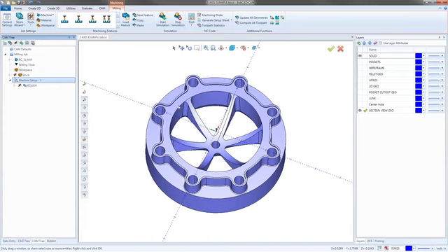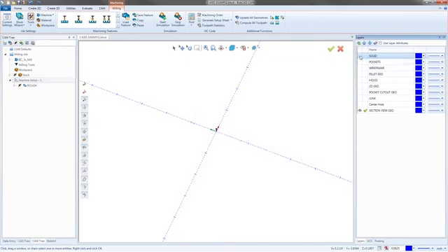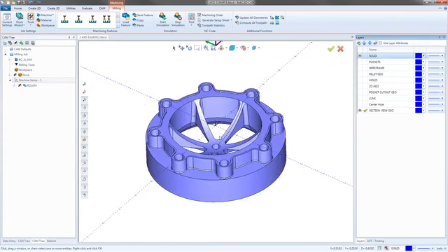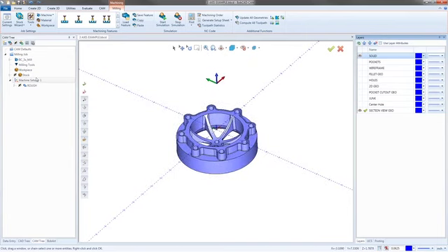So, but before we could do that though, for me to machine this kind of ledge here, I'd rather it just cut all the way around, just kind of do a circular toolpath that cuts the entire dome shape. So what I want to do is construct the surface for that kind of dome shape. Now I've already made a layer for it. It's called the section view geo, and it's a function that I'd say is probably one of the most overlooked.